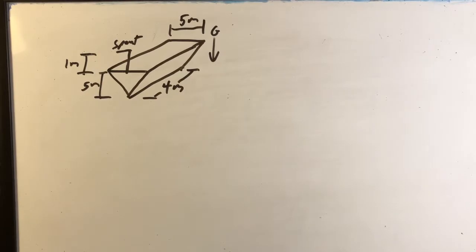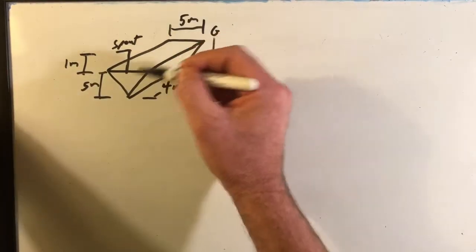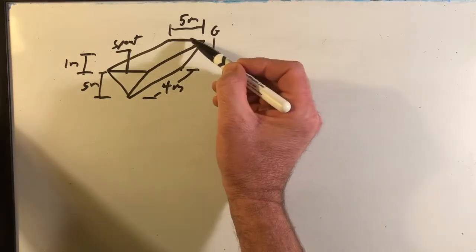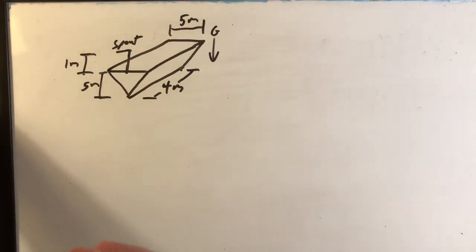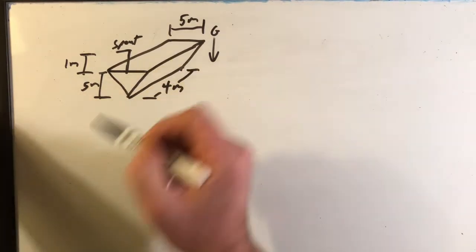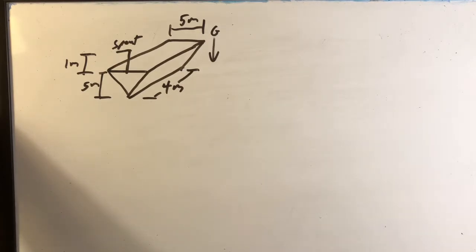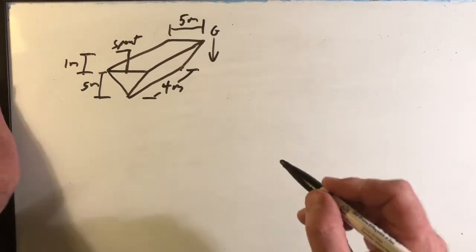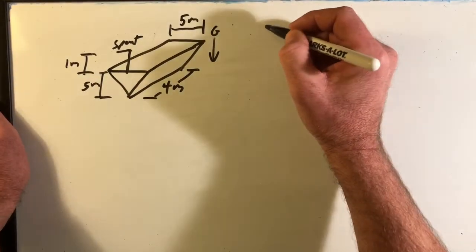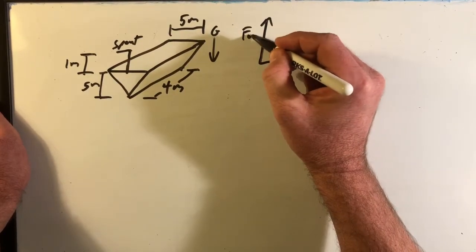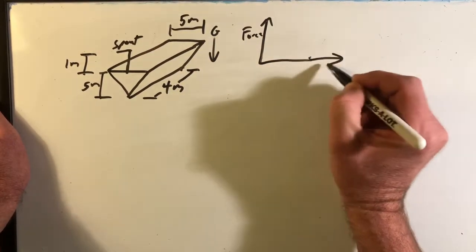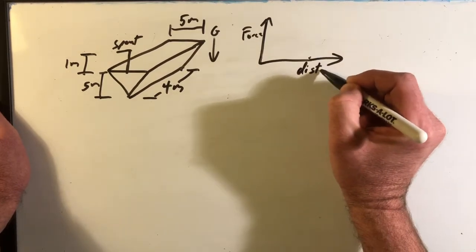Okay, and then this distance from the spout, we'll just say that's 1 meter above the top of the tank. This is a great problem because things aren't quite natural here. If you are drawing liquid from here, you're going to have this whole surface, and it's going to draw down this way. So it's not like your typical volume calculation. You have to stop and think about it for a little bit. Ultimately you want to get to where you have force, and then distance along this side.